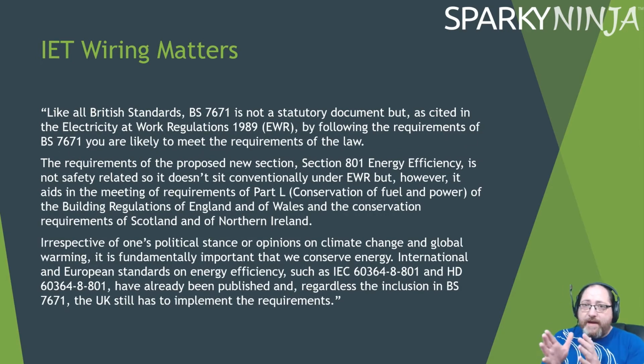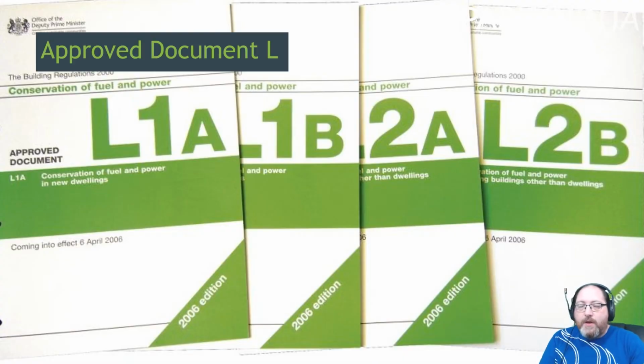It's also mentioning that, like all British Standards, it's still not statutory, and with regards to the requirements of section 801, it's not actually safety related, and so it doesn't sit conventionally under the Electricity at Work Regulations. It's going to sit more under the building regulations, with Approved Document L for the conservation of fuel and power. But if you've done building regulations study, you'll know this, and you'll be like, yeah, a lot of this stuff we've done because of Approved Document L. There are 4 of them there: dwellings, non-dwellings, new, not new. Those have stated the changes over many years now that we should have on our installations, and we've been putting them into practice quite often.